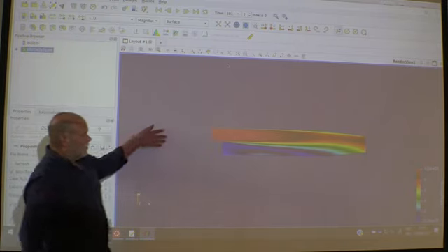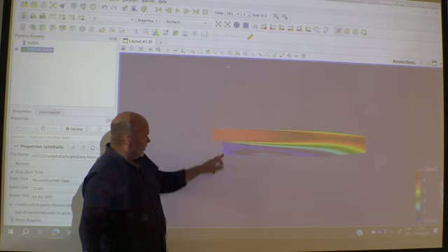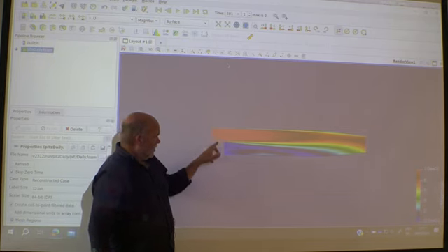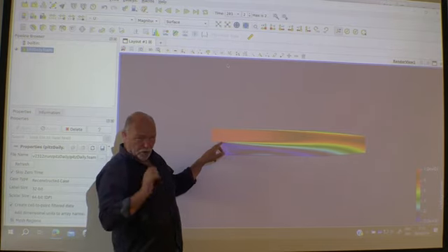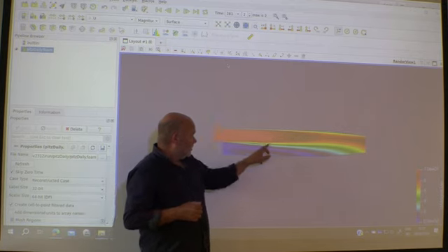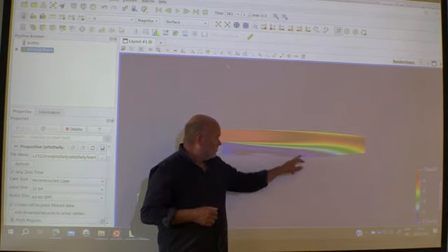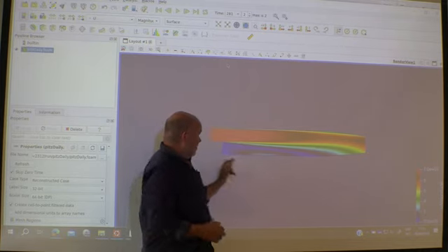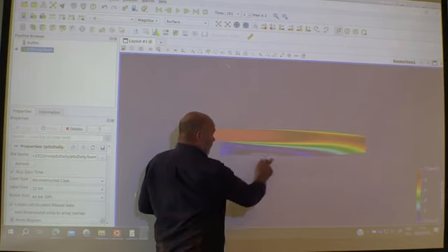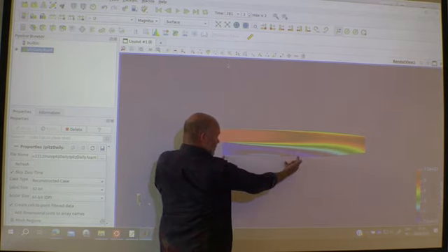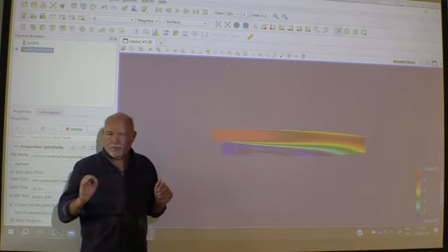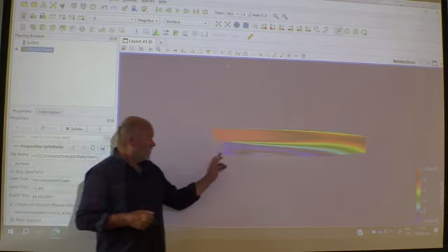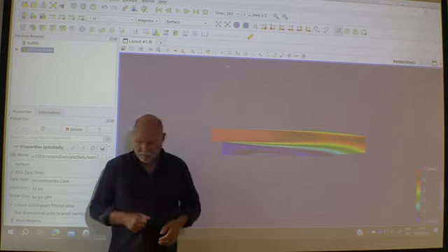So you're sending in a constant velocity here, and here you have the backward facing step. And you can actually think of it as a streamline starting here at the corner of the step. It will then stop somewhere here, because here you have one big vortex. And this distance, scaled for the step height, there you have your reattachment length. That's the one we are seeking.